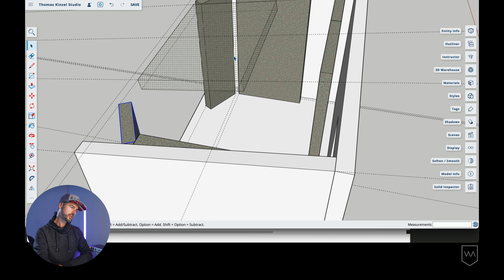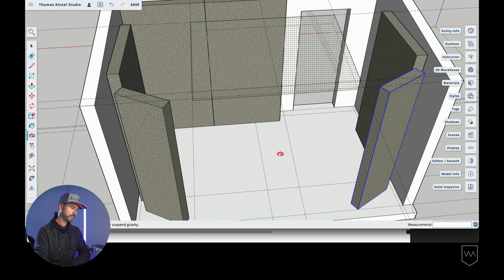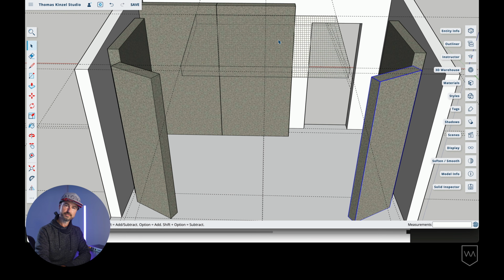I'm using a 2-inch thickness of Rockwool cavity rock in this case, and that's it. That's kind of all we could do. We were stretching our budget already, and I oriented these in 2-foot wide frames that are 87 inches tall. These ones are going to straddle the corner, and they're not even going in at exactly 45 because we didn't have the space to do that. So they're in at a 30-degree angle. But what that is going to do is create an airspace behind them, and that's going to increase the low frequency absorption. So we're just getting more treatment into the room, more absorption, and we're using these strategic air gaps wherever we can. Sweet.